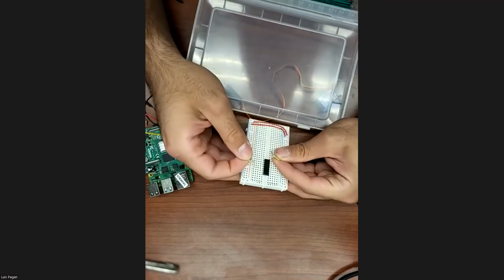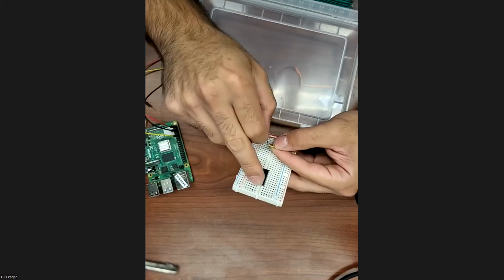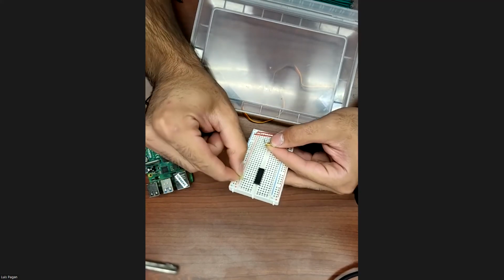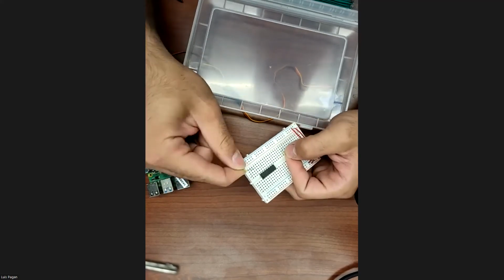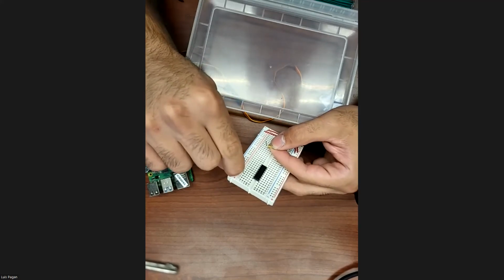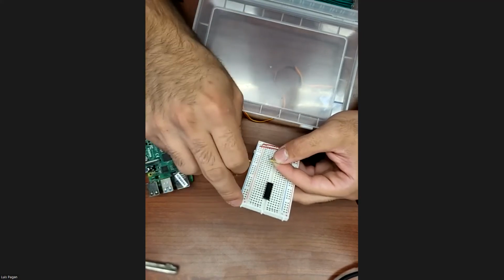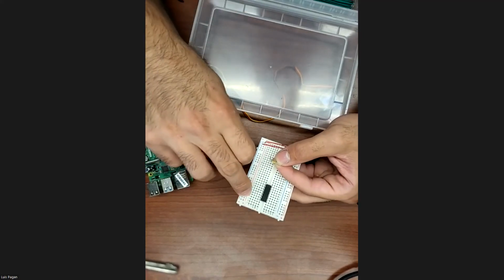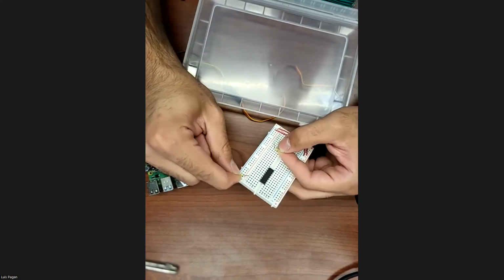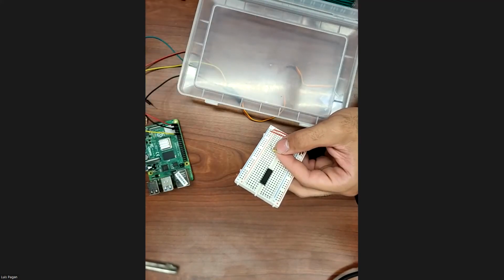So we want to start off with the power to the board and the power to the motors. If you remember, this pin up here was actually the power to the board. What you want to do usually is make sure you plug in as far away from the chip as possible, so you go from the outermost lane towards the middle, which means maybe this piece is a little too big, so I'm going to get a smaller one.